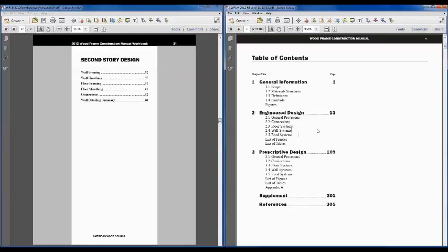And I think I mentioned this last time, but in the standard, we sort of work from the foundation to roof, and that's the way the code's laid out. But in the design process, we work the opposite way, from roof down to the foundation, to make sure we can transfer loads and ensure our load path down to the foundation. So we kind of work backwards in the document, and so that's a little bit of a twist for how the standard is laid out versus how we work through the example.